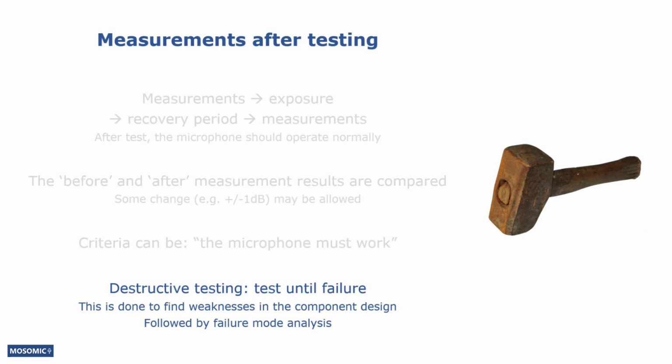In some cases, the test may be continued until all, or a certain percentage of, the tested microphones have stopped working. This kind of destructive testing can be used to find weaknesses in the component design. The testing can be accompanied by failure mode analysis of the tested components.